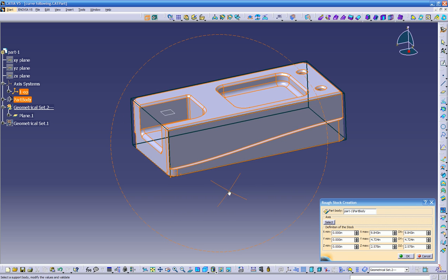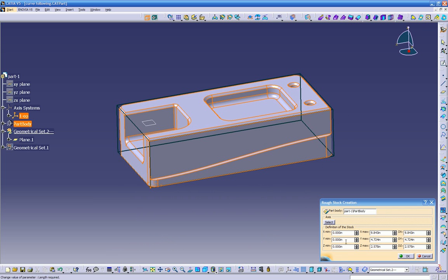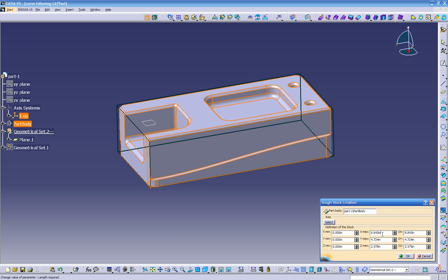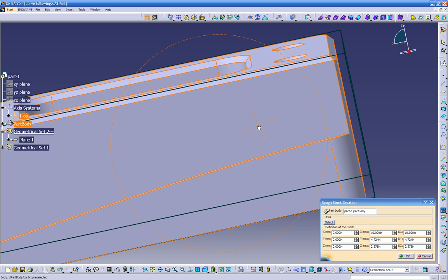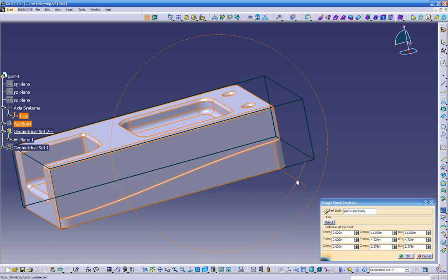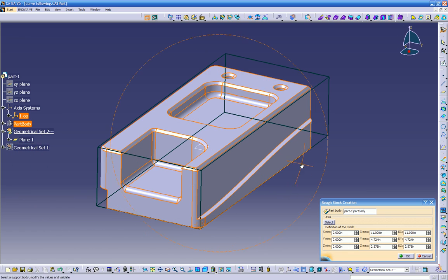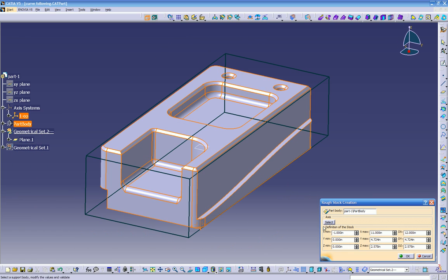But if the stock is bigger in real life, you can come back in here and change it. So right now it's 9 inches. For example, if your stock is 10 inches, you just type 10, and see, automatically it's increasing your stock. See the difference right here? It's making it bigger, so you can see you have a couple options you can choose from, and also over here.